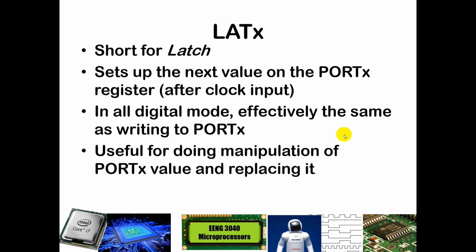Latch corresponds with port A through port E, and the X here also follows A through E. This is short for latch. The input and output logic is based upon a digital latch, a D flip-flop. This is what allows us to read the current value coming out of that flip-flop, which, if things are an output, is likely exactly the same as what should be coming out of the latest port update. But if things are inputs, this allows us to access some things directly off the flip-flop without having to worry about whether the proper output is coming.